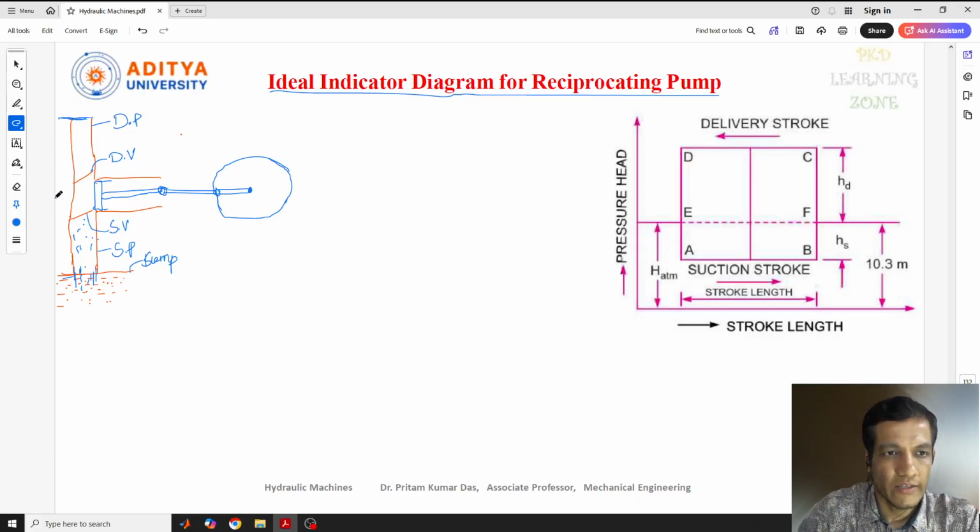If you consider this as the center point of the cylinder, then this distance is nothing but the suction head, and this distance is nothing but the delivery head. From the center point of the cylinder to the point where the water needs to be delivered, that total distance is called the delivery head, and the distance from the sump level point to the center point of this cylinder is called the suction head.